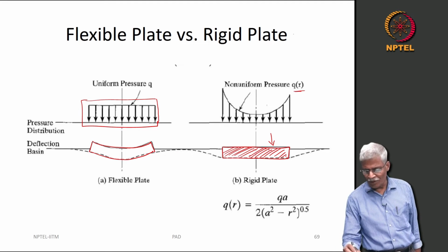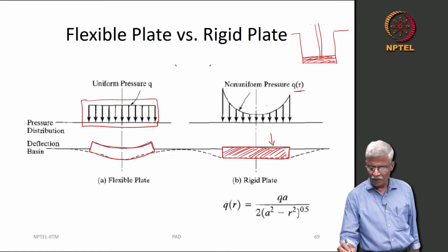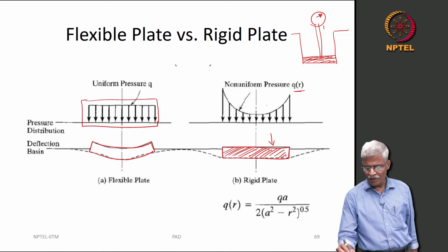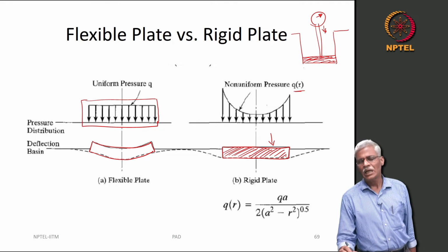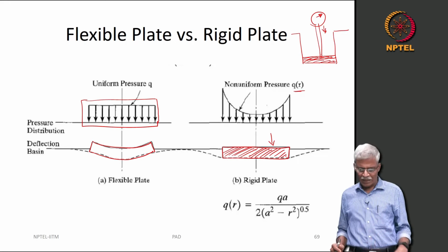Normally, you need to think of it this way: we take a trench, put a plate here, with a dial gauge, and keep applying load and measure how much the plate is moving inside as a whole, because this is a rigid plate.